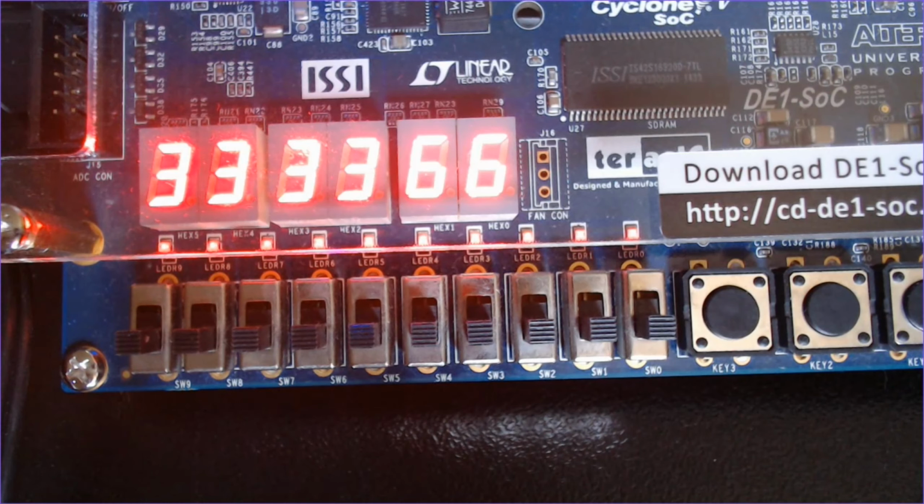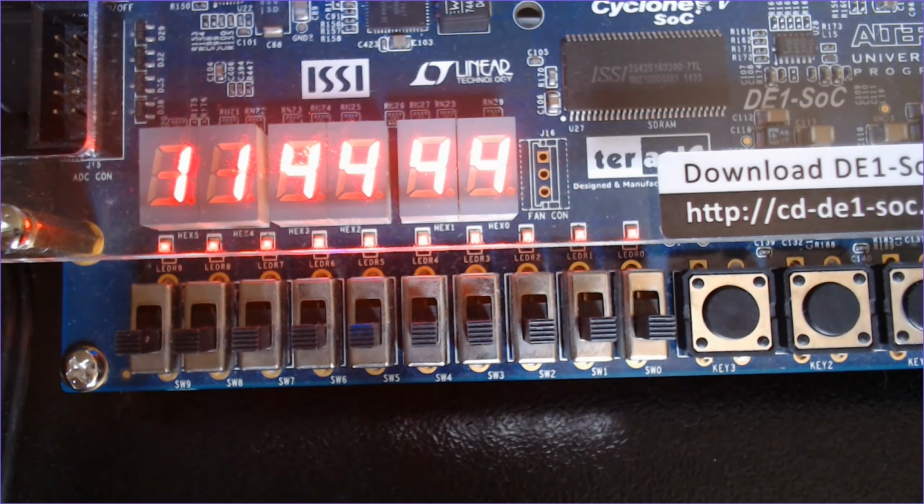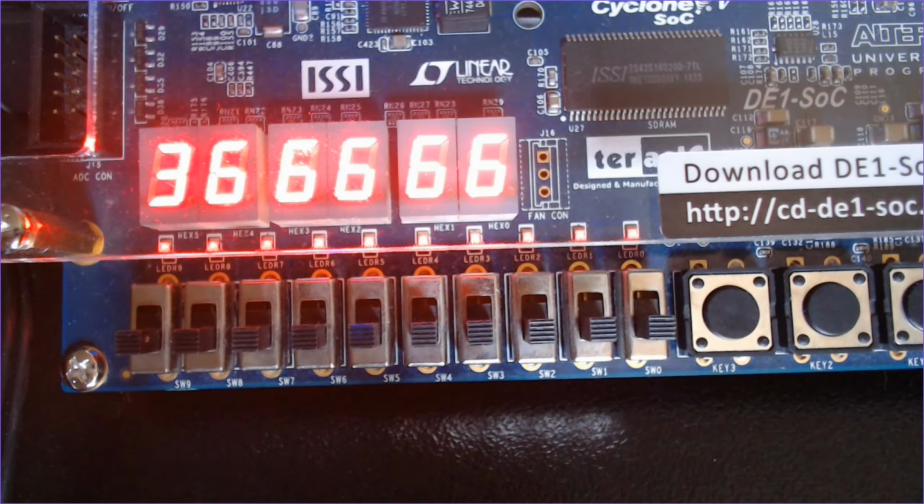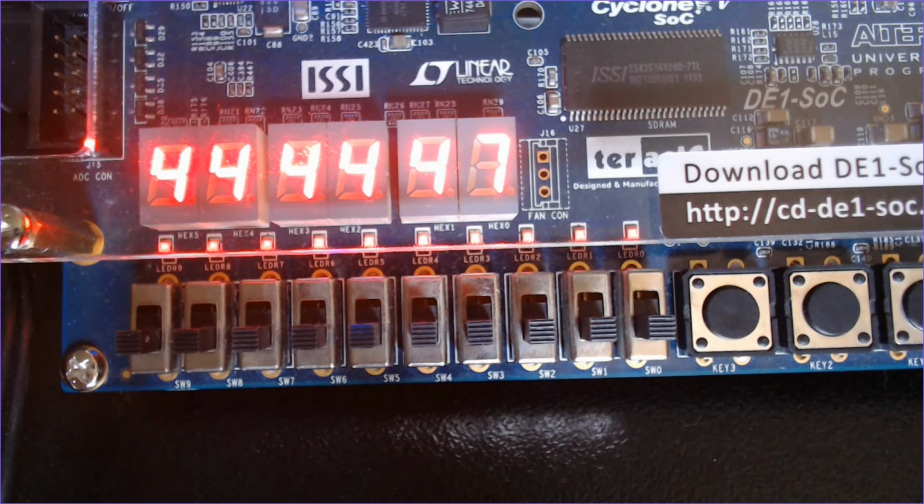We have got the numbers changing at an offset. So you see first one number changes, then another, then the next one, it ripples through. So it shows you that everything's working. And each digit, if you look at it, is a +3 modulo 10 counter, and each one is just offset. So each digit should change once a second, and they're nicely offset to get the effect that you're seeing here.